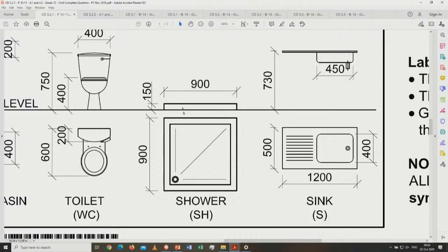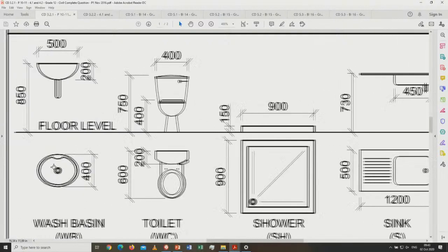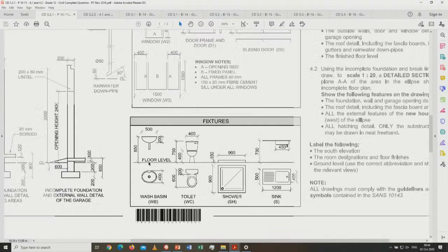Here's the shower. Again, there's nothing on top, although there's glass sometimes on top or whatever the case might be. Nothing shown. It's just like a concrete block on the bottom where you will climb on. And then for the shower itself, it's showing you double lines and all the fancy lines going to the plug and so on. So leave out those lines. You know the symbol. We have done the symbols for that. The toilets, all the curves with the toilets are shown. For the wash basin, again, it shows you a funny-like bottom tail part where the piping is going out. None of that is necessary. It's a rectangle with a circle inside there. All right, so that is very important that you have to show.